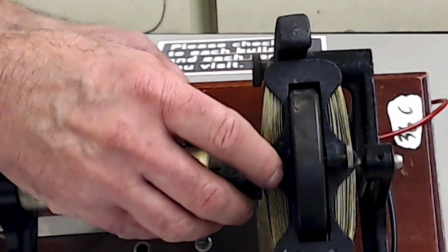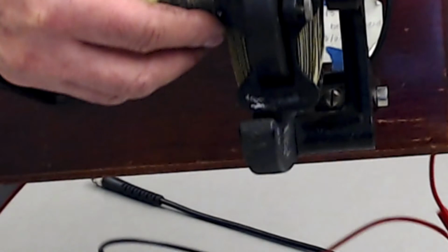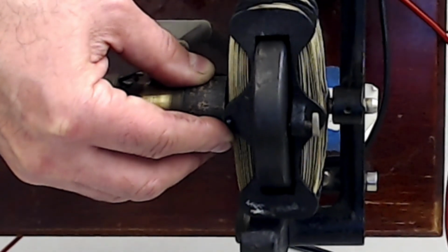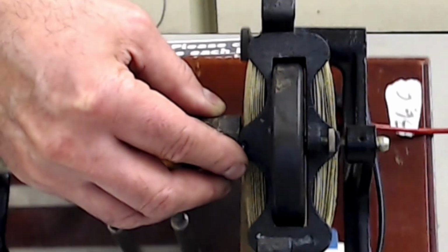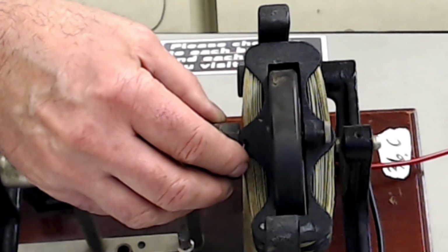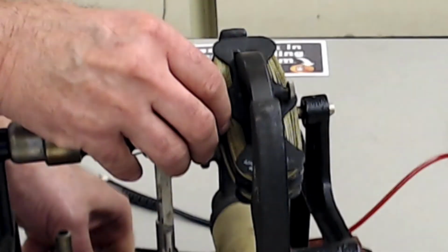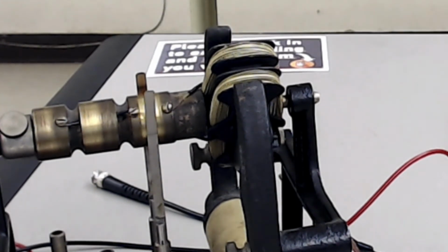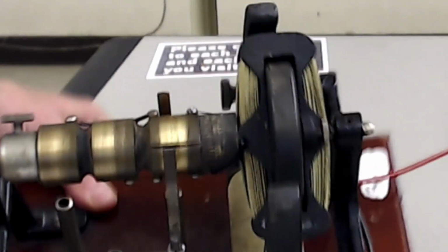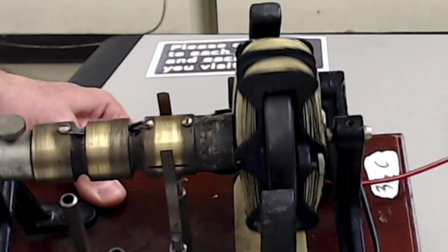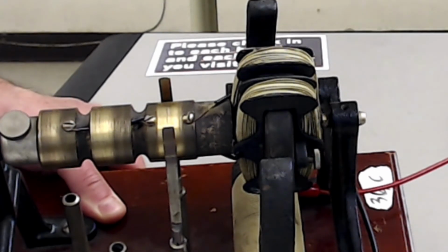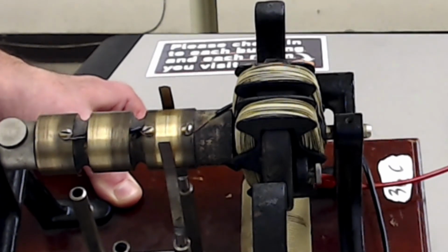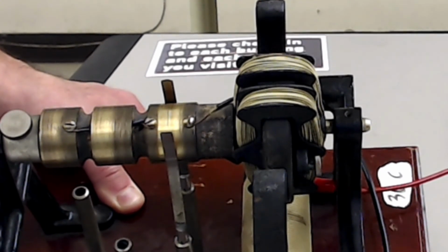The magnetic field, if I rotate it like this, is either top to bottom or bottom to top. And so the torque is a maximum. Because remember, in the cross product, when the two vectors are perpendicular to each other, the value of the cross product is maximized. Because this thing constantly rotates, the magnitude of the torque, the cross product, is constantly changing.